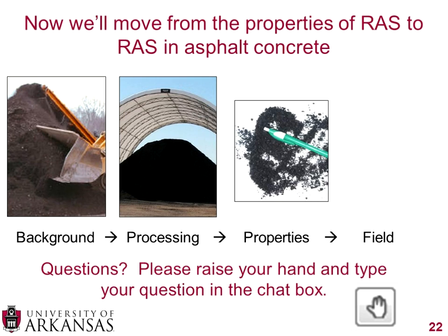So the next question is from Marty Burrow, and the question is, can you blend recycled asphalt shingles asphalt cement with a softer AC of known grade and back calculate the RAS grade?